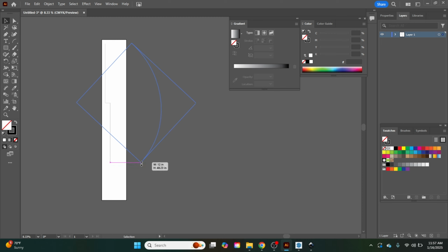Most important part of CAD anyways is making sure that it's a closed section. So what happens is this is too far of a bulge. So what I'm going to do is straighten it up and move the whole thing in to where it touches the bottom and the top.